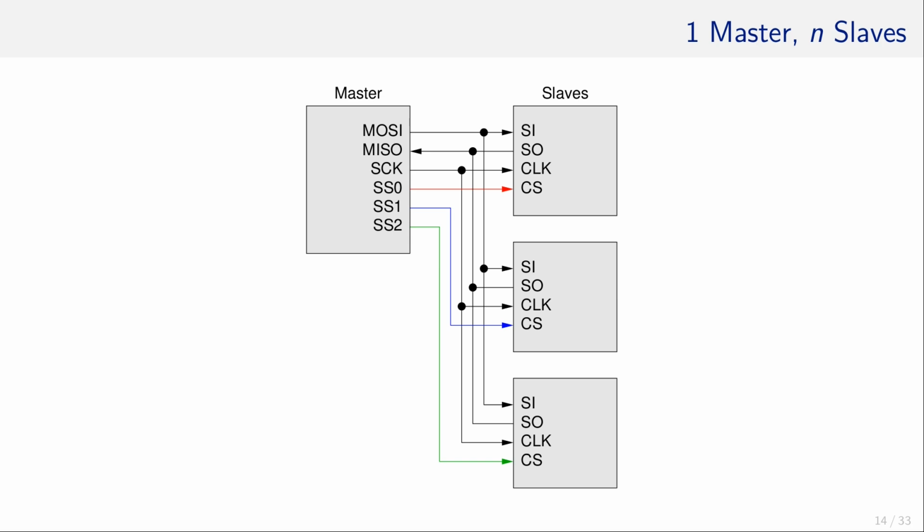First, the data is jumbled because multiple slaves use one wire connected to MISO. Second, what happens if a slave wants to write a 1 to the MISO line, but another one writes a logic 0? That means the first slave wants to charge the wire, while the second slave discharges the same wire. We have a short circuit.